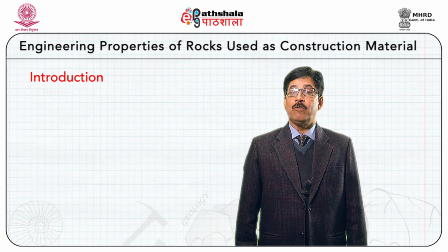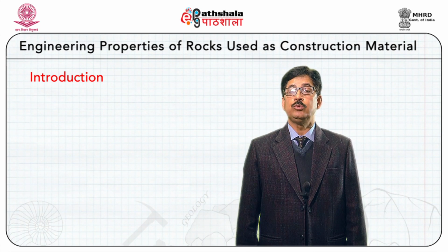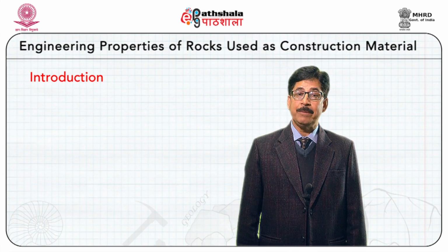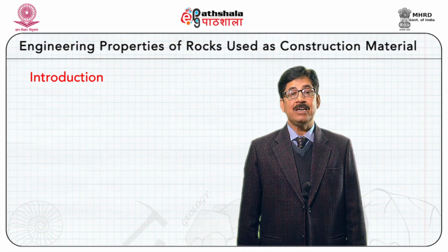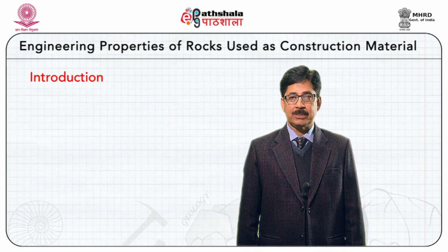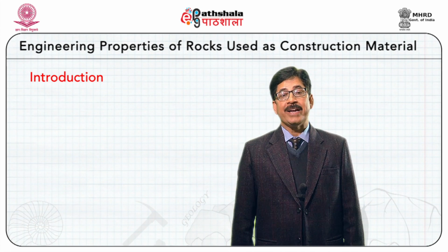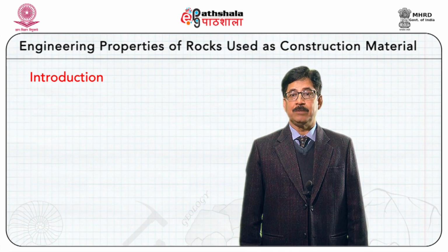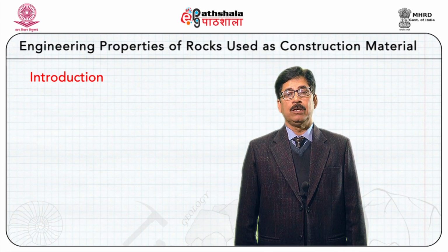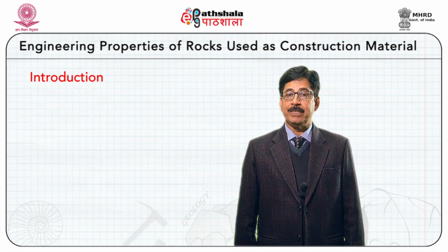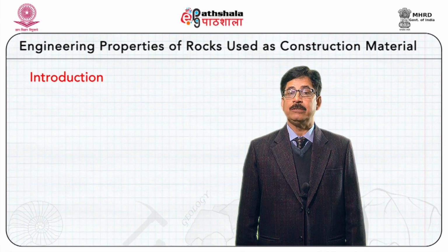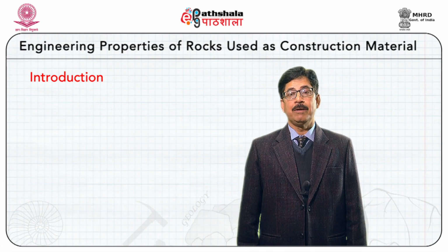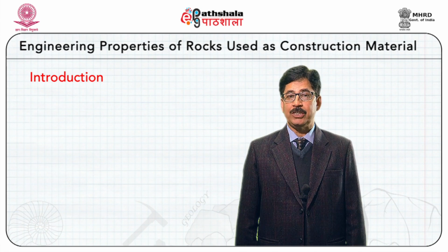Now, when we talk of rock mass, where we are going to use rock at its original place by founding some structure over them or by making some structure inside them, then we call them the founding rock or site rocks. We have different physical, mechanical and chemical properties termed as geotechnical properties, which broadly depend upon physical appearance, strength and stability of the constituent minerals, how they have been interlocked with each other within a rock, presence of layers in terms of bedding, foliation and fractures.